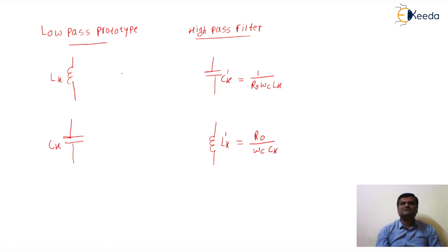How do we transform these? We transform these by using frequency scaling and impedance scaling techniques. Thus, by using these techniques, we can easily transform a low-pass prototype filter design into a desired filter.